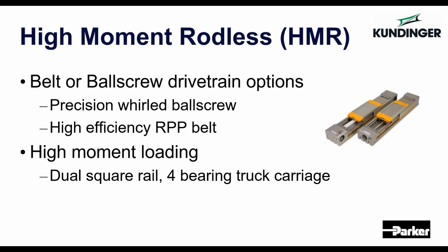So the BHD is a pretty simply designed product. You can see by the cutaway image we have there, you've got two pulleys, one of which is fixed, one of which is a moving pulley to apply tension to the belt, and designed around square rail type bearing. So there's really no kind of precision alignment needed. Everything is floated in just due to some of the way it's been designed and some of the machining processes we're utilizing. It does utilize dual trucks